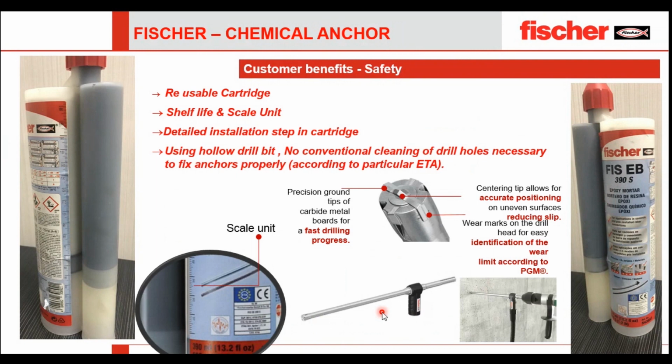It means if you are having a renovation of a hospital, over there, there are many serious cases and you cannot make the dust fly. And you know that when you are using a chemical, you should make sure that you have done blowing, you have done brushing, you have done cleaning accurately. So to make sure of this, you can use this hollow drill bit where the particles will not at all be there, where the dust will not at all be there. So you can use a hollow drill bit, which is more efficient for this application. So you don't need one more guy to supervise or for cleaning or for brushing or any other things.